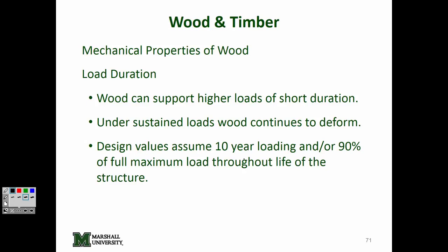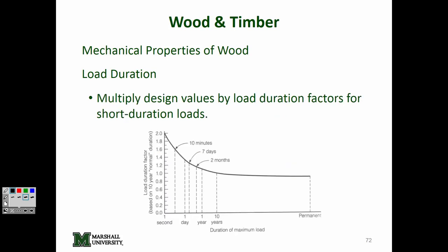Load duration, the longer you load a piece of timber, the more you have to worry about what kind of load you're putting on it and what kind of deformation it's going to get. I've been in buildings where the timber was 100 years old, had some pretty good sags in the ceiling just from its self-weight over 100 years of hanging there. And this diagram shows that very phenomenon. If you were going to design something that was going to only be loaded for 10 minutes, you can use a higher design load than if you're going to design something that was going to be in place for 100 years.